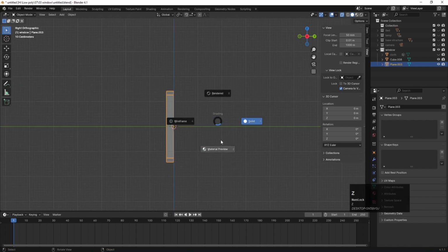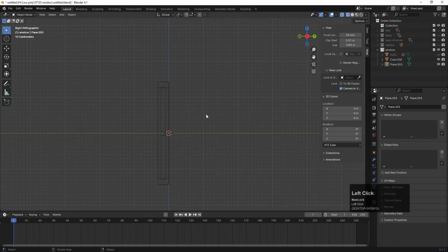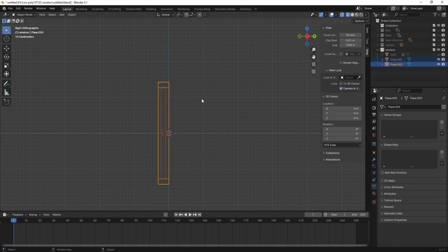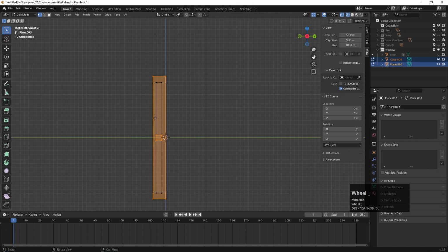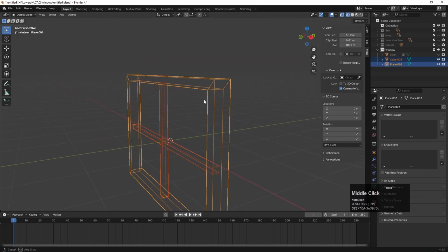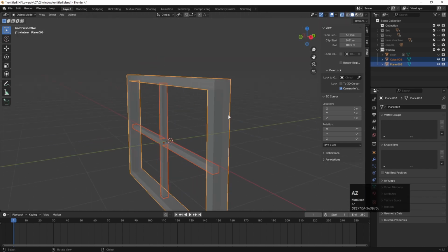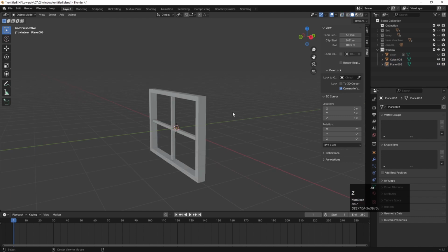Also if you want, then you can go to the right view as well, press Z and choose wireframe view so we can see. Let's select all of them and press tab to select these edges. Okay, we will keep it as it is, not gonna change anything over here. Then Z and choose our solid view again, and Alt Z.